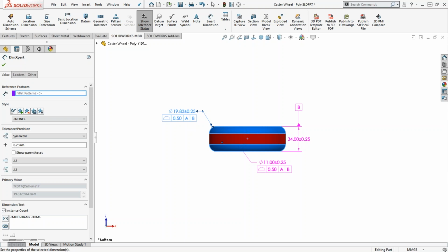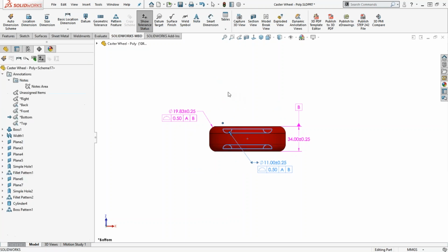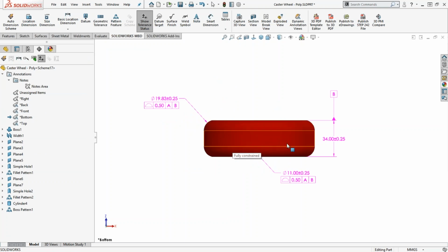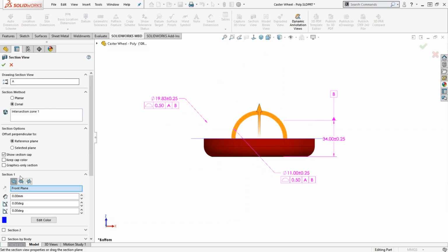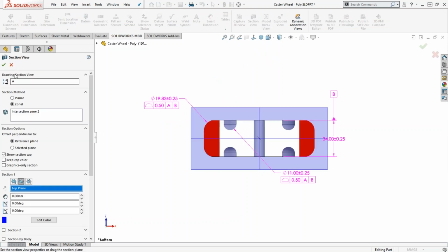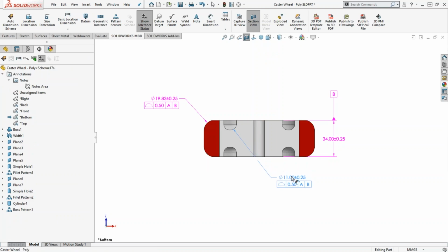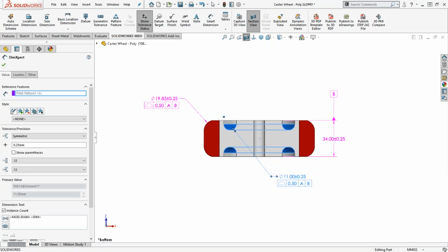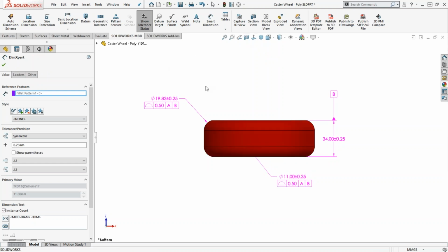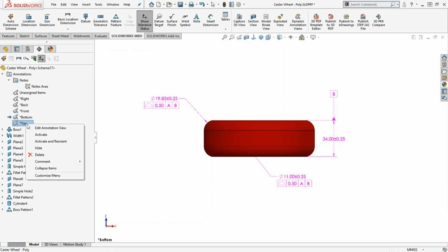And we can see here that I don't really like the way that this is being attached, because this fillet that it's detailing is obscured. So in this case, I just want to activate the section tool real quick just to make sure that everything's attached and looking how I want it, because when I capture the 3D view eventually, I'm going to capture it as a section view. So, all right, that looks good on the bottom view.